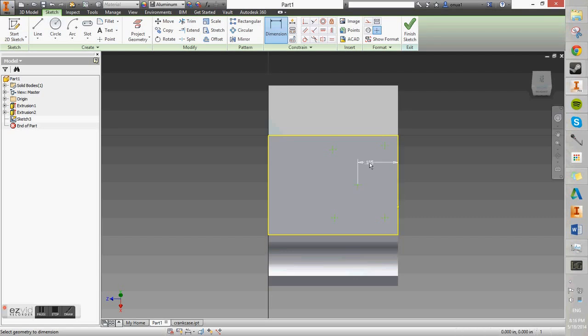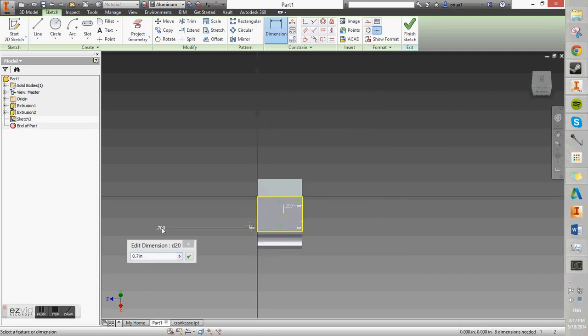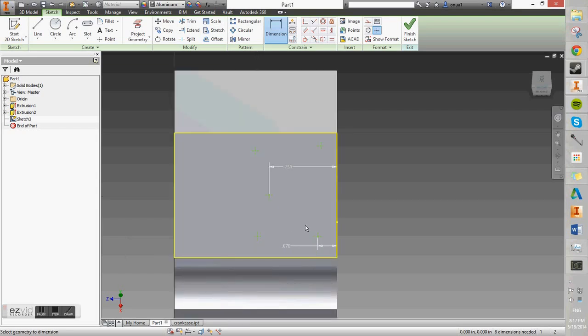And when we originally placed it, we saw a little dashed line showing up from the edge, telling us it was in the midpoint of that side. So we're safe on that dimension. It auto-constrained it there for us. So let's just constrain this side point to 0.07. Whoops, 0.07, not 0.7. Okay. That looks a bit better.